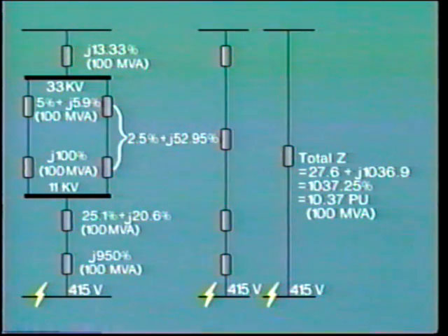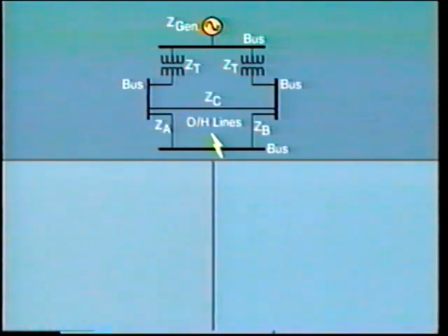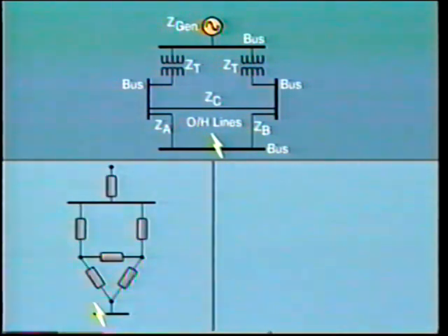So up to now, we've seen that it is fairly simple to calculate the impedance values and corresponding fault values for a radial circuit. However, in practice, as we know, networks are considerably more complicated and often consist of several closed ring systems like this. In order to study this system, the first thing we need to do is draw the equivalent circuit, calculate equivalent impedances, and then step by step simplify as far as possible.